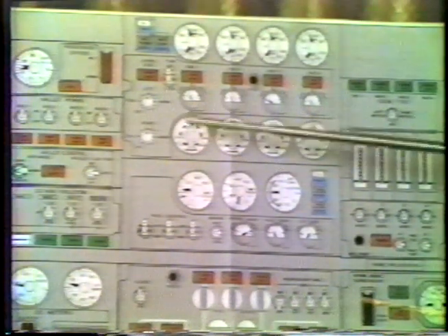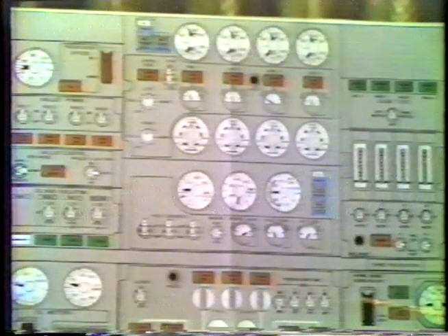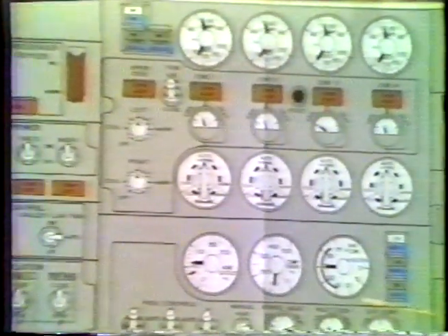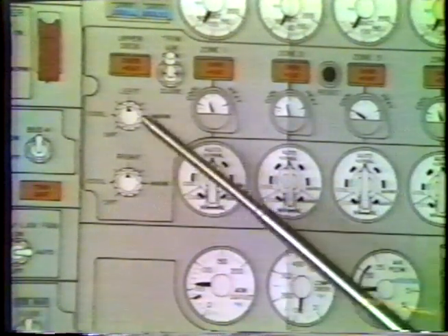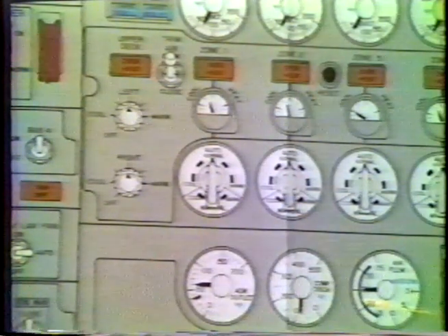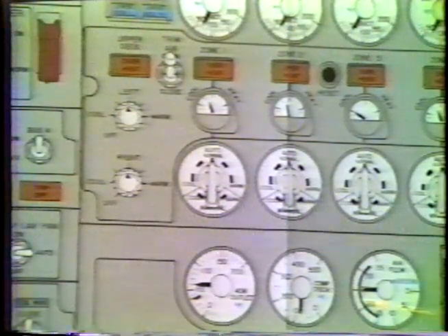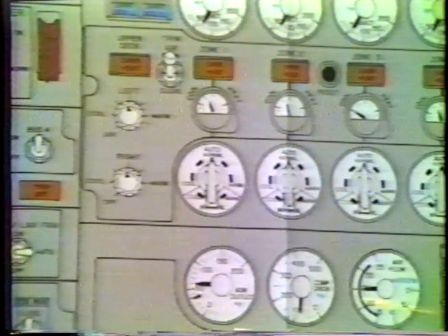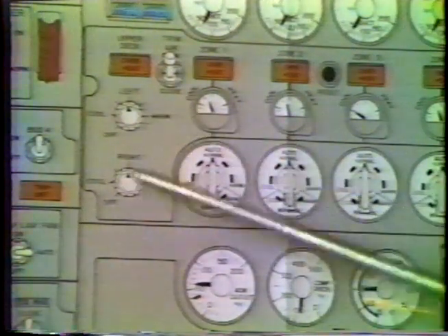Alongside the temperature controllers, we have 2 knobs here for the upper deck heat. Instead of running trim air to modify the temperature of the air coming to the upper portion of the cabin directly behind the cockpit, Boeing has decided to put in electric blanket heaters, and the temperature of those electric blanket heaters is controlled by the position of these knobs.